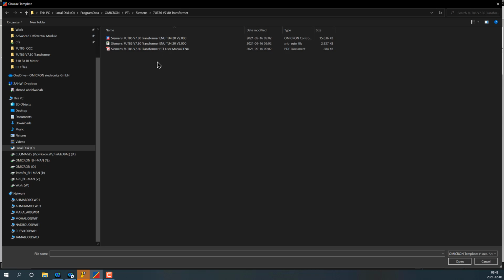People familiar with our scripting can change some equations or parameters. We recommend you change everything here in the XRIO converter, and later import it to the OCC file to maintain the test module Omicron made for you, and later you can add your own module as you want.